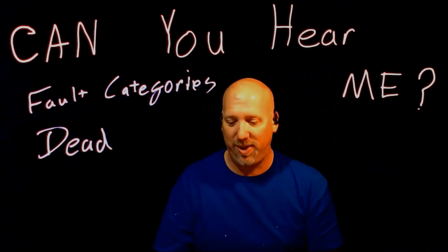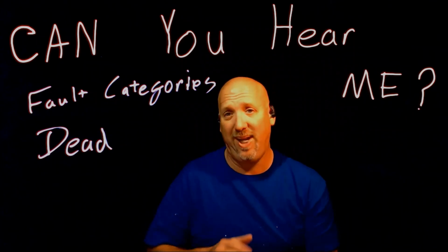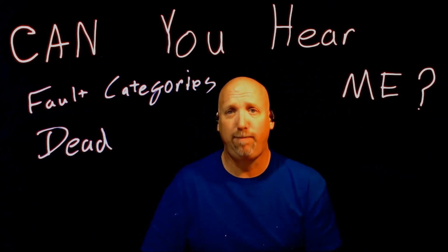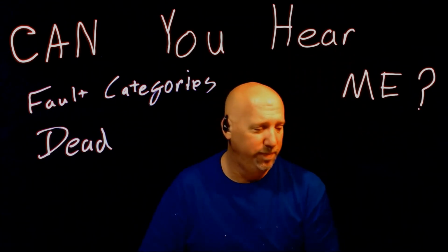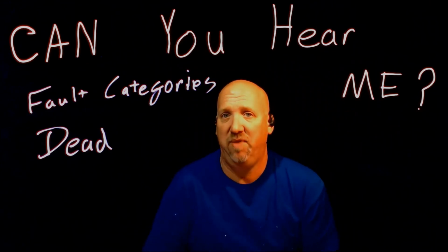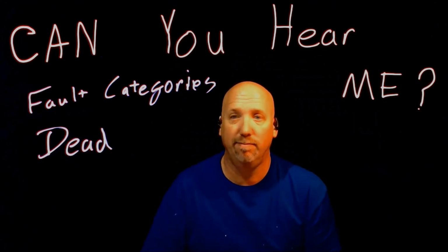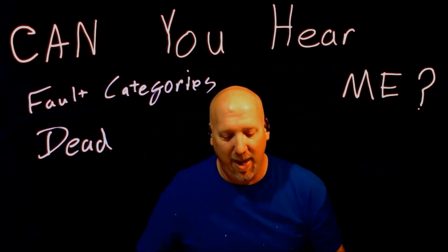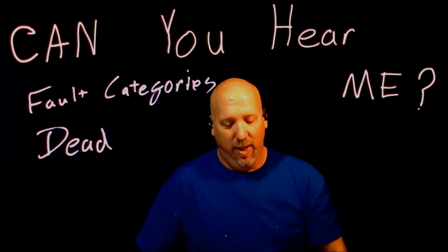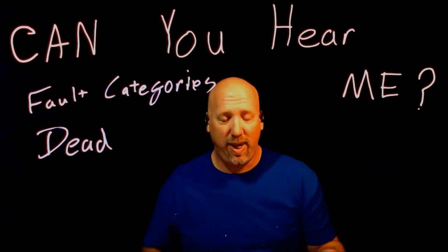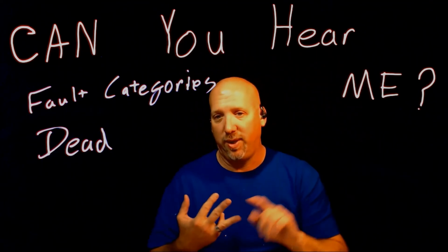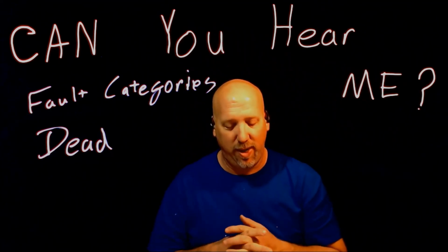I've seen people decide to check module communications with the key turned off. It's hard to get information if the key's turned off, because the vehicle doesn't know it's supposed to be on. Will the module wake up? So be aware of that, in the case of finding power, ground, and the switch ignition states, making sure all that's right.